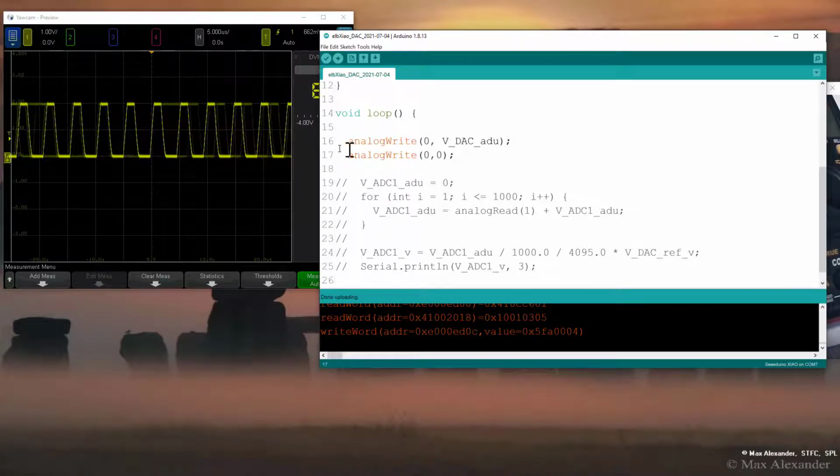We see the ghosting. We can eliminate that problem by telling the Xiao, hey, don't look for interrupts. The command is no interrupts. But the USB commands on the Xiao also use interrupts. And so if we tell the Xiao module, hey, turn off interrupts, it will forget how to use the USB port. And that means it won't communicate with the USB port and it'll brick.